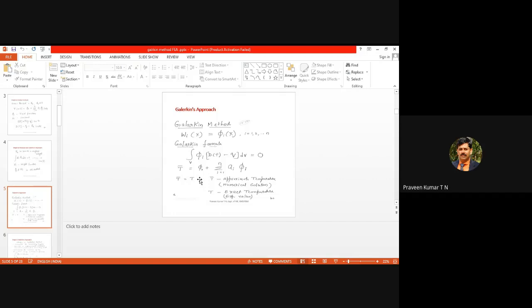So you are starting from this equation, the Galerkin equation, and we have phi. The function phi is nothing but a temperature function. In heat transfer, inside the derivation, there is a term phi. So phi refers to the temperature function, or nodal temperature vector.